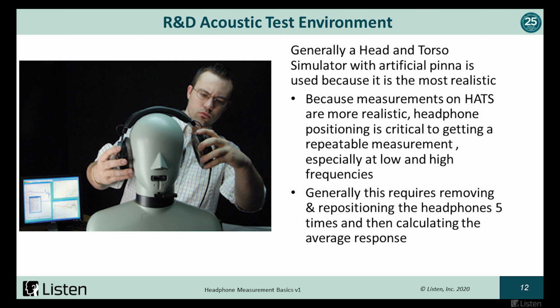So for R&D, generally I recommend using a head and torso simulator with pinnae because it's the most realistic. The other thing to keep in mind is that the more realistic the head and torso simulator is, the more important positioning becomes, especially if you're trying to compare measurements between 2 different headphones, or even measure the same headphone on 2 different days. If you don't line up the headphone correctly on the pinna or in the same location, you can get a drastically different response, especially at the low frequencies.